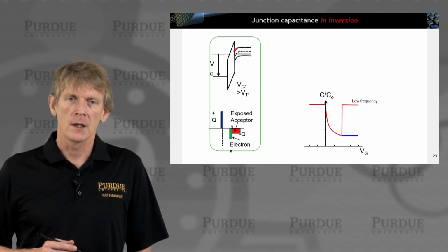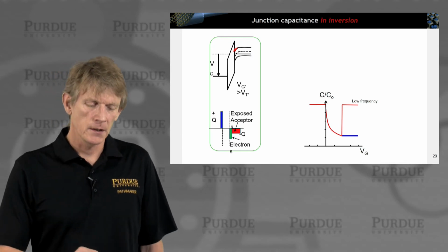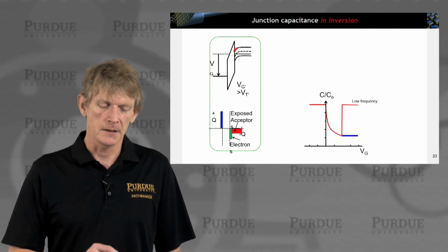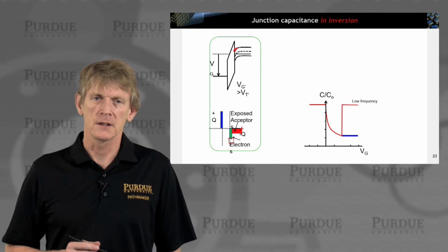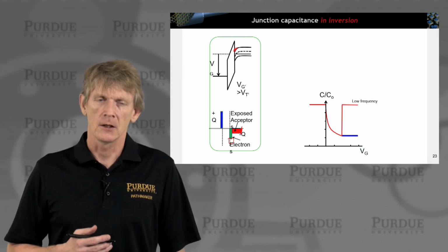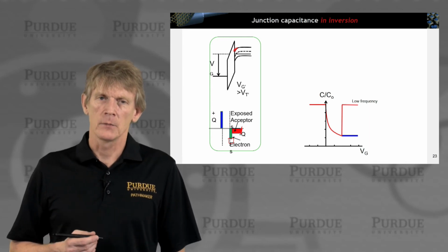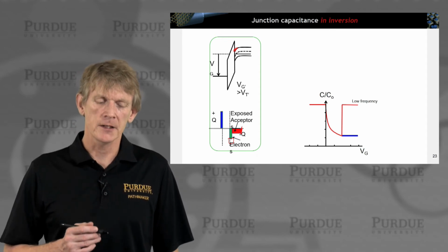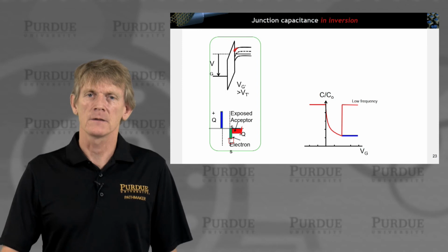That will minimize the overall energy stored in this capacitor, and therefore, instead of wiggling electrons and holes at the tail end here, you will just add electrons here in the inversion. Okay, that's the low energy point of the charge stored in the capacitor, because that maximizes the capacitance in the system. So we're really only looking at differential electrons that are minority carriers in the semiconductor.